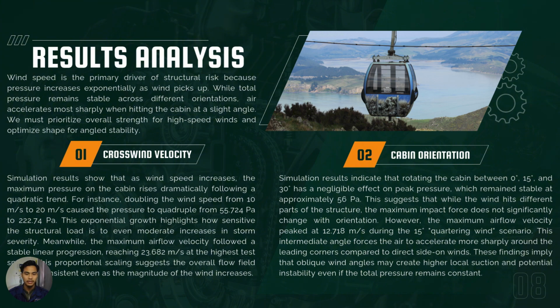This intermediate angle forces the air to accelerate more sharply around the leading corners compared to direct side-on winds. These findings imply that oblique wind angles may create higher local suction and potential instability even if the total pressure remains constant.